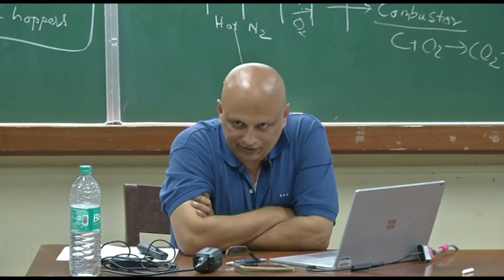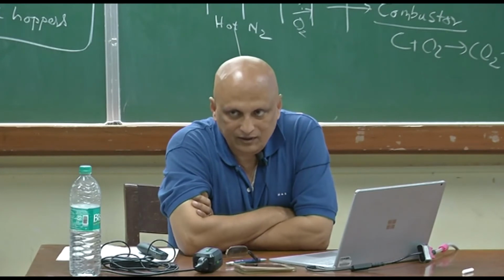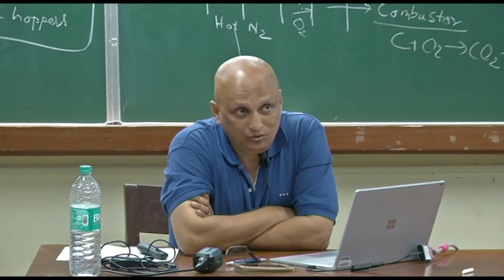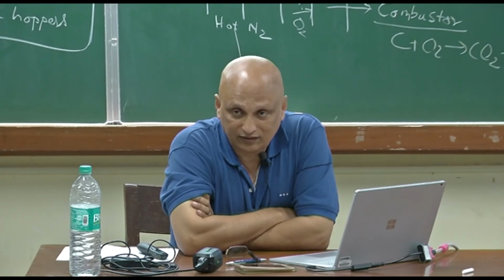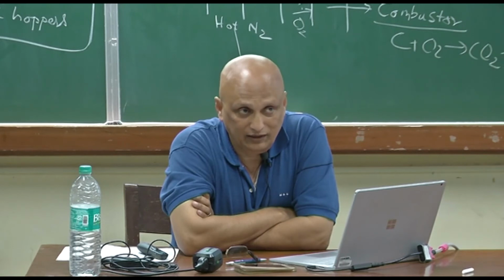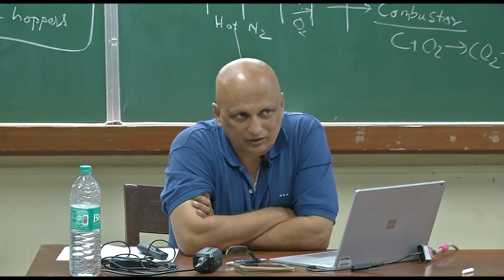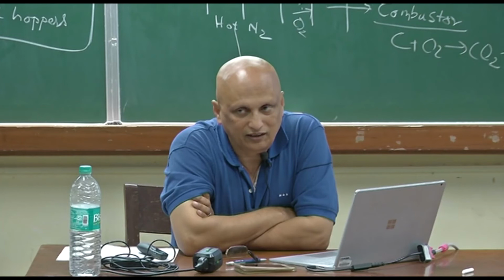Correct. Compared to the kinetics of CO2 gasification. Yeah. So in the slides where I presented Tao Shu's work, I can't remember which one, maybe lecture number 4 or something, that's where we had CO2 and water, CO2 and steam mix. Yeah. So usually steam conversion, steam reactivity is about 1.8 to 2 times the CO2 gasification reactivity at 900 degrees.